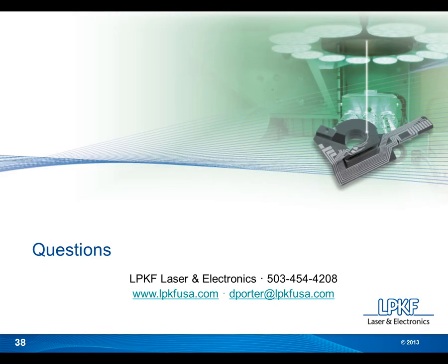Also, in terms of tooling cost for the lasers itself, we have a lot of possibilities there. We can use prototype tooling, which is basically an instant made putty material for individual parts if we do prototypes, or for mass production we can use fairly complicated fixtures that are really designed for very high throughput. Those toolings of course are more expensive than a simple prototyping tooling. So again, tooling cost varies very much with the type of use we want to get out of this tool, if it's a very high volume mass production consumer electronics part, or if it's an item that we're just going to make a handful of for a specific prototyping application.